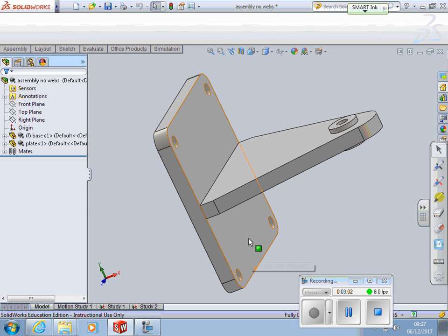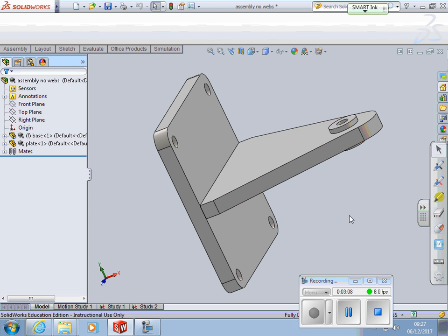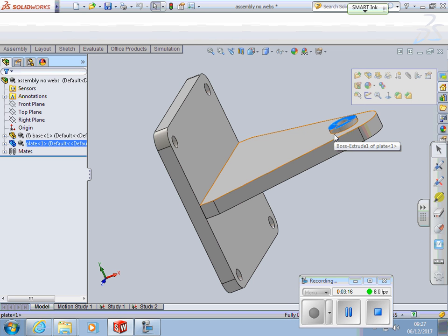The assembly consists of this base, that plate with a boss on it. What we're going to be doing is looking at applying a load to that top face and assessing how that affects the bracket, and considering the most important thing we're going to consider is factor of safety. So we're going to apply 15,000 newtons onto that top face and look at how that would affect this bracket.